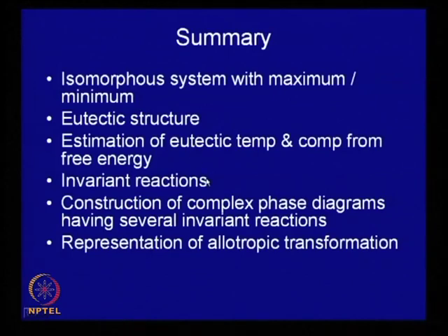Then we looked at several invariant reactions, and broadly these invariant reactions have been classified into two groups. In one, a particular phase dissociates into two at a particular temperature, and in the second category, two phases react together to form a third distinct phase on cooling.